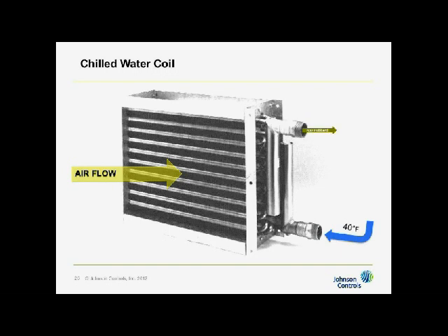That's how it works. These very corners of the coil that you see here are the places where the coil starts to get dirty. And as it gets dirtier and dirtier, it'll form sort of a donut shape, where the very center of the coil is clean and the very edges of the coil are dirty. So if you had a light on the other side of the coil and you looked through it, you'd see very light in the middle and kind of a donut getting darker and darker.